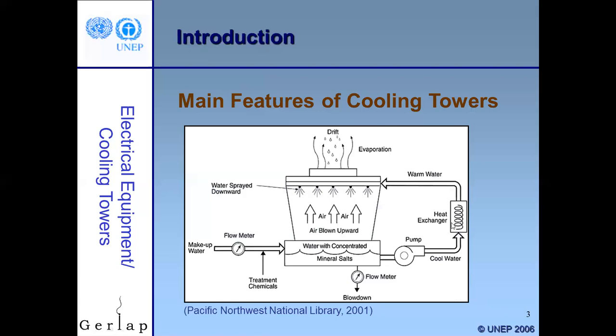So we're pumping cool water, which is initially in the basin, has already been through the tower and is cooled down. Design numbers, at least in the old days, have typically been 85 degrees coming out of the basin and 95 degrees coming out of the chiller being supplied to the top of the tower. Once at the top of the tower, the water is distributed out in troughs.